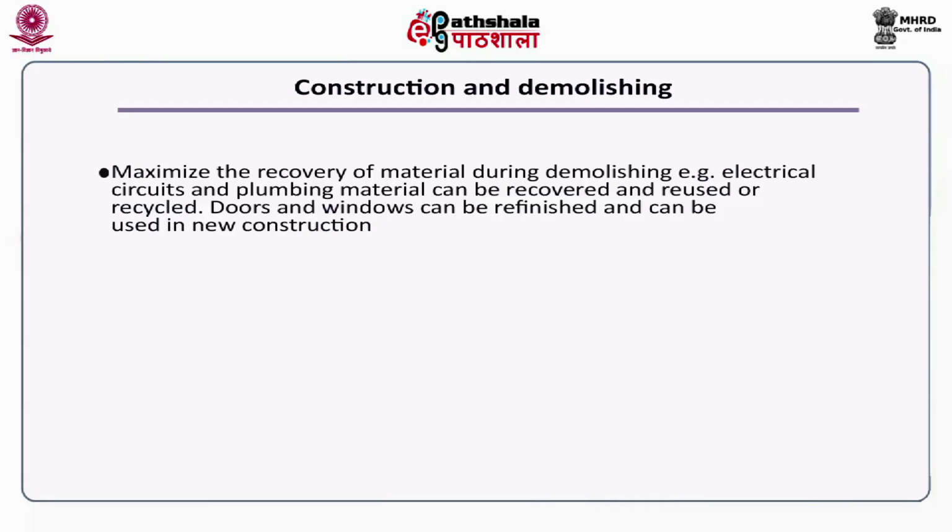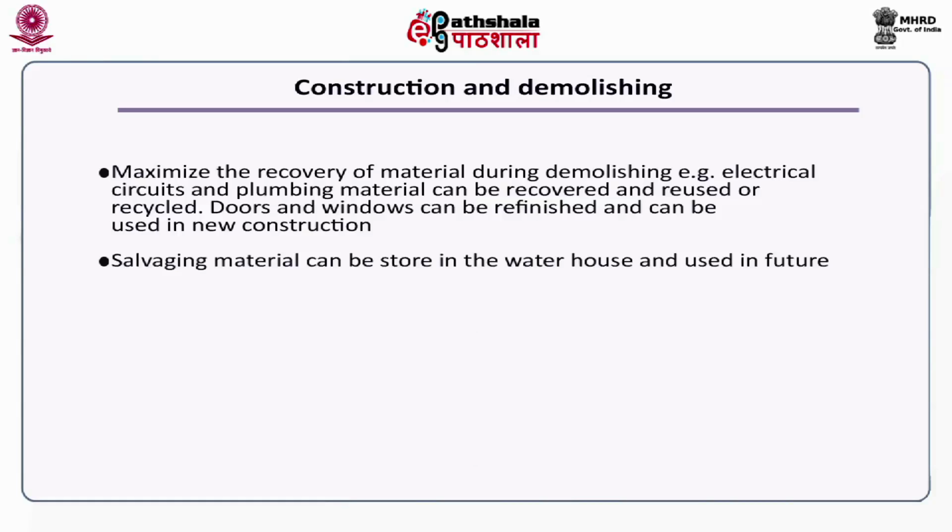So, maximize the recovery of material. Likewise, when you demolish a building, you can maximize the recovery of material, like the electrical circuits and plumbing material, all these can be recovered and reused or recycled. Likewise, doors and windows can be refinished and can be used in a new construction. Salvaged material can be stored in the warehouse and can be used in future.